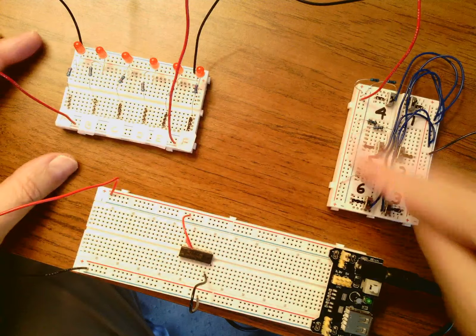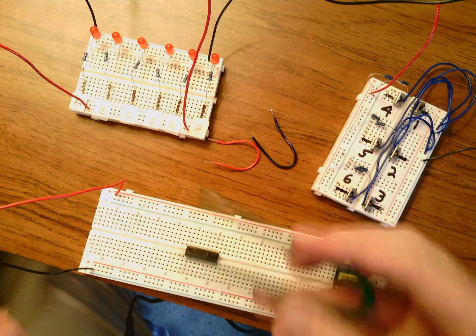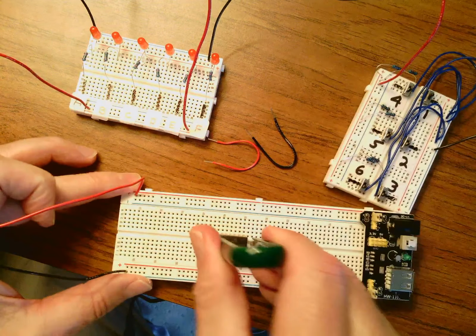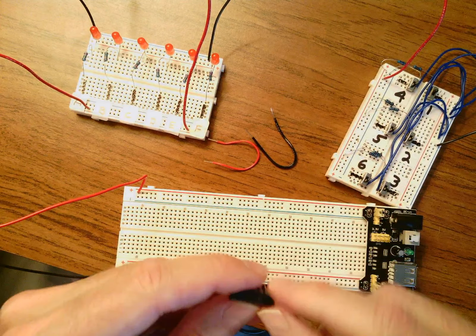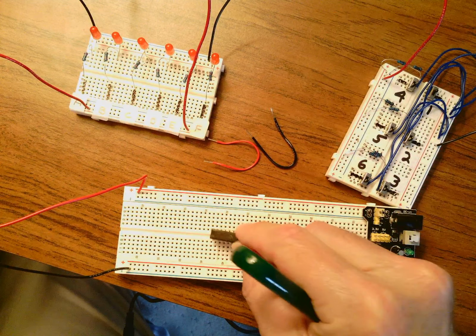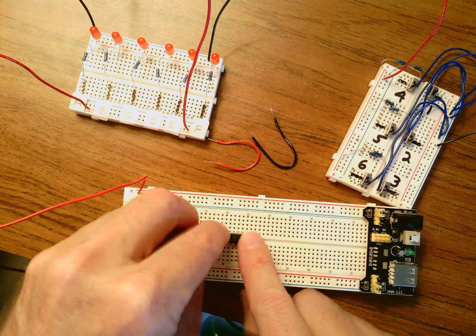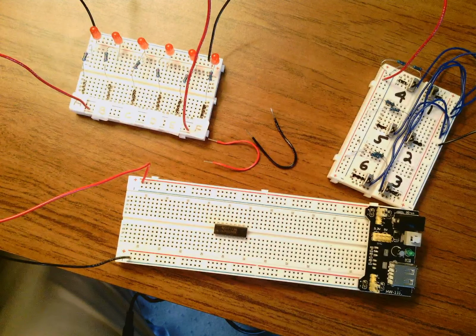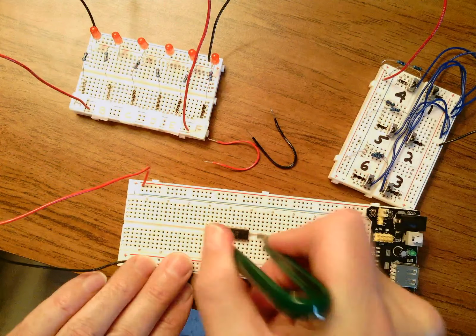When you remove these chips, be careful. If you bend these pins a couple times, they'll break. That's why I give you a chip extractor. This little green chip extractor, what you're going to do, there it is. You're going to put it on each side of the chip, and you're going to rock it back and forth very gently, and you're going to remove the chip. And always inspect the pins, make sure they're okay. Now let me put it back in here. Make sure they're lined up, press it in, make sure it presses in the whole way. Now, use a chip extractor and you can very carefully take these out.